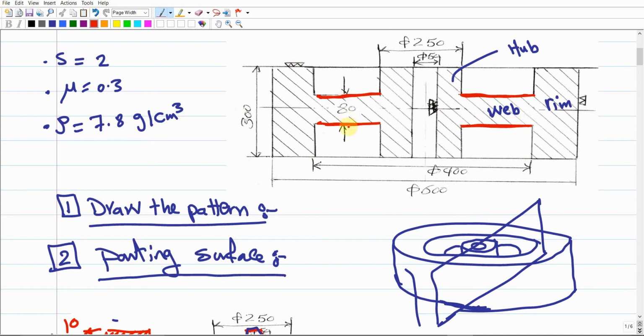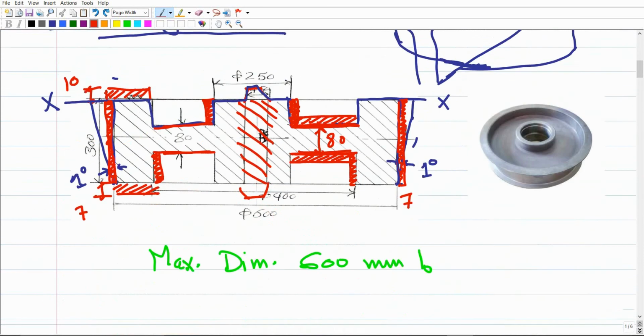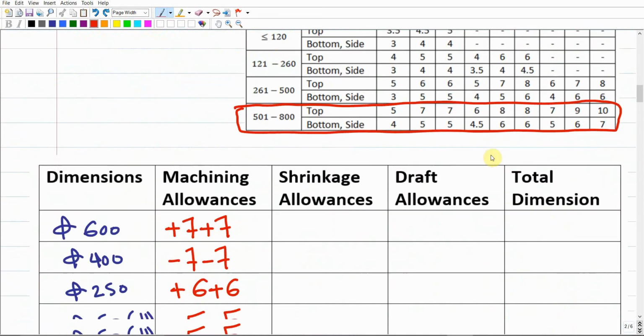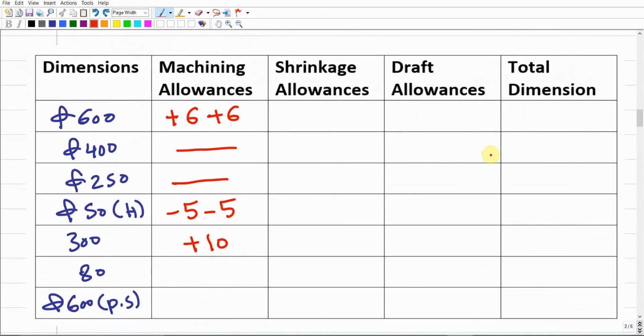But these two or these two are different. Anyway, none of these four lines has any machining symbols, right? This indicates that we won't add any machining allowances to the array, so there is no machining allowance. Just add one big dash next to the array.